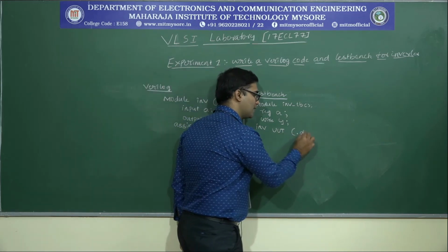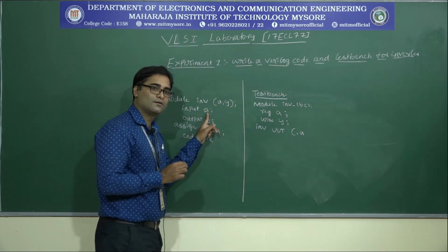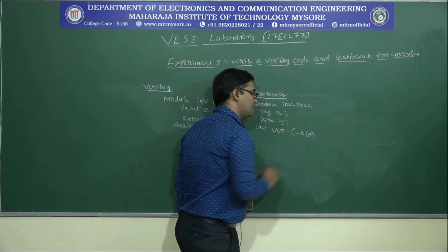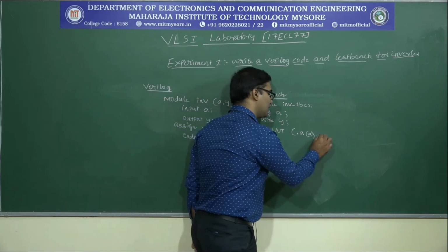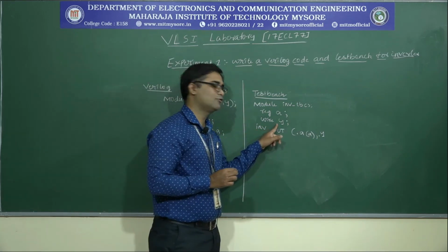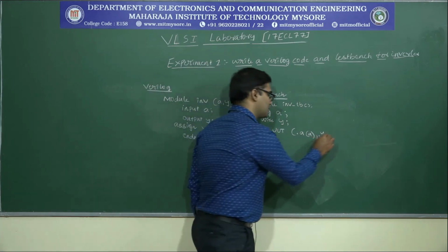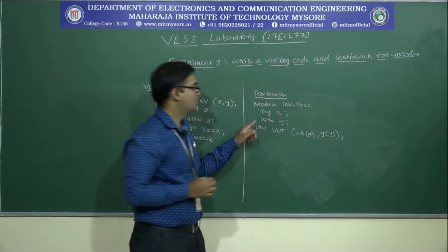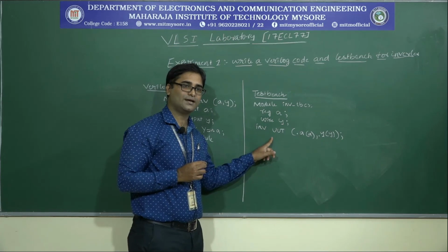Again, interlinking, we have defined A of the Verilog code, and we connect the test bench input, which is defined as a register. Next, the output Y, and the output with respect to the test bench is defined as a wire, Y. So this is the instruction called the unit under test.